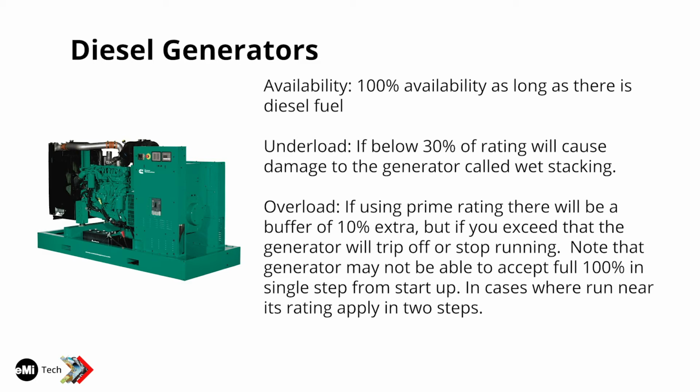It's important to understand that if a generator is underloaded for long periods, which means under 30% of its rating, then it will cause damage to the generator, and this is called wet stacking. You don't want to way oversize your generator because you will have problems with it over time. And I'll have some more slides to show what that looks like later.